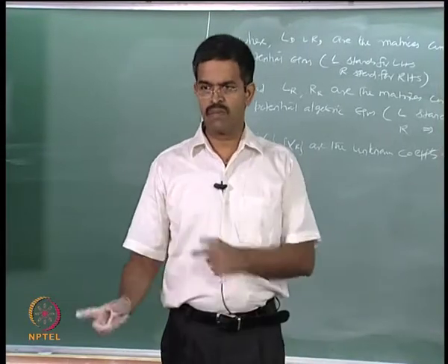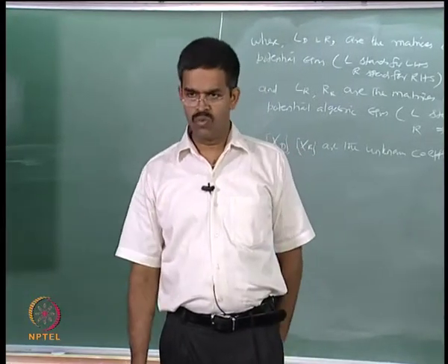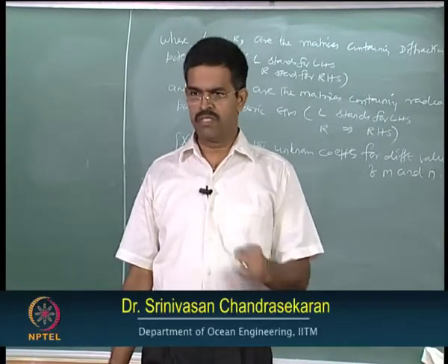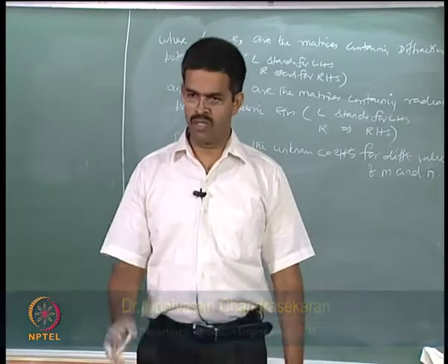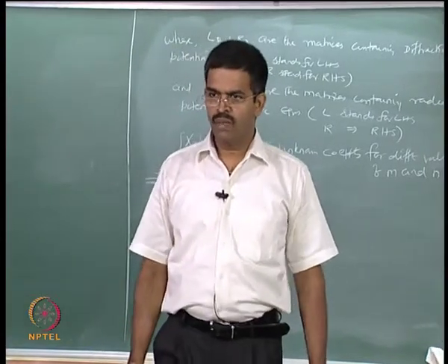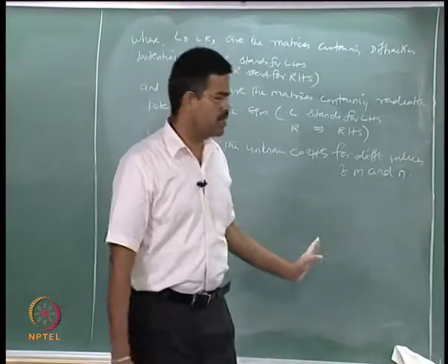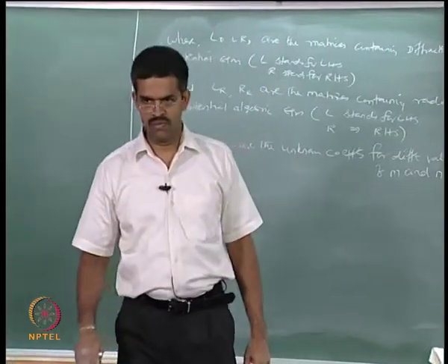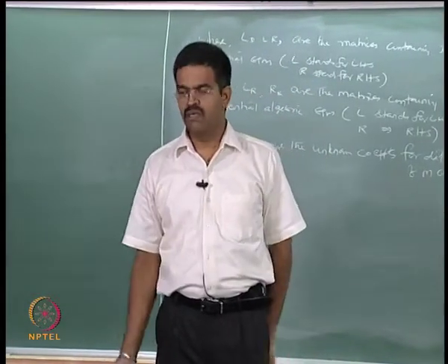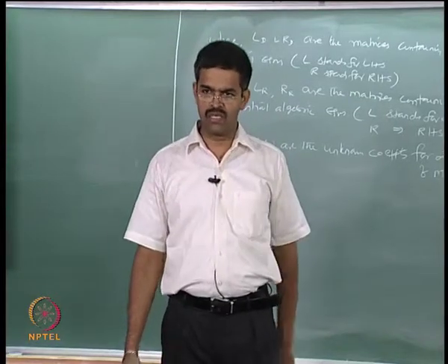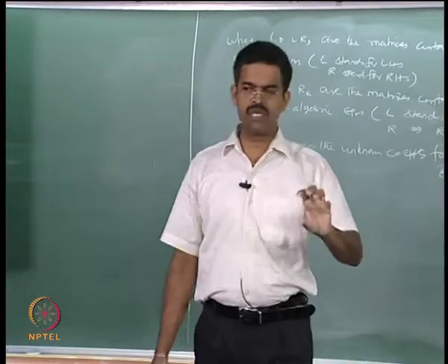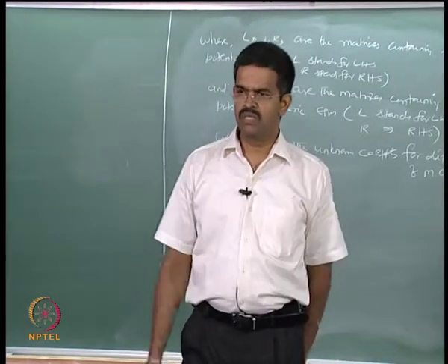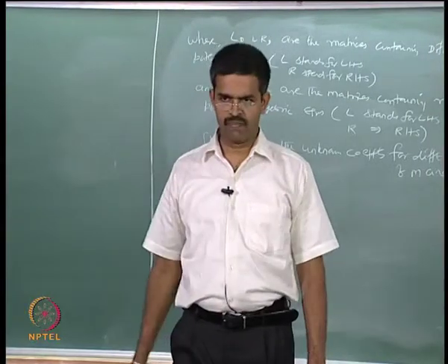Okay. This was attempted in the previous lecture through a numerical example using Star CCM+ and an experimental investigation which was done on a scaled model of 1:140. Obviously, you will not be able to validate all the 3 results on a given example problem, because these are all different types of approaches. So the results may not get validated, but an attempt was made to show you in the last lecture how closely the experimental studies and the numerical model are validated, with a small error of about 5 to 7% or 10%.